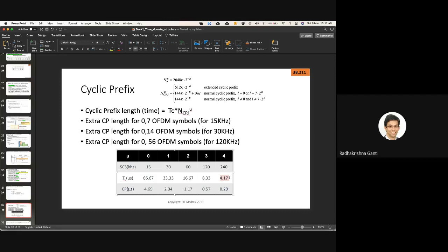They chose 60 kilohertz subcarrier spacing. That is the right region, because for small cells the distance is very small. In that situation, multipath delay spread is less. And in FR1, since 60 is the last subcarrier spacing, there is more delay spread, and the symbol duration is very short. So for that, I think this is the reason.